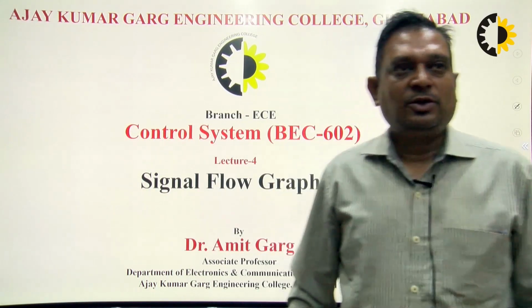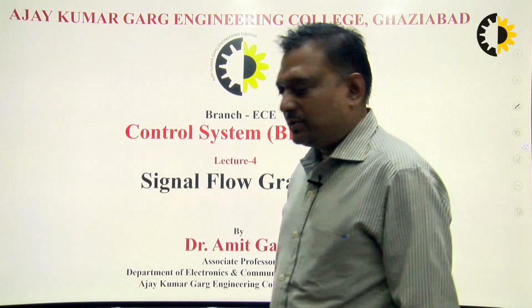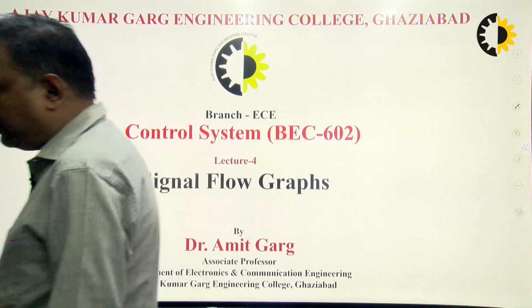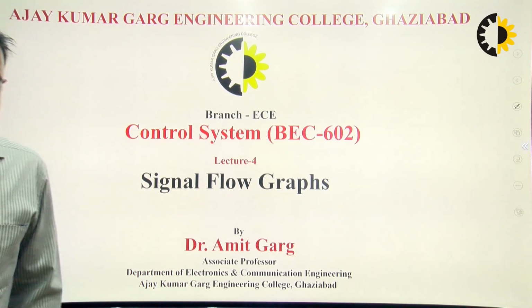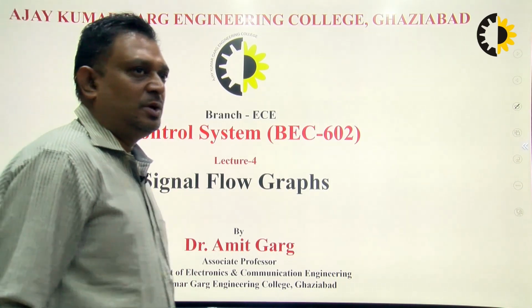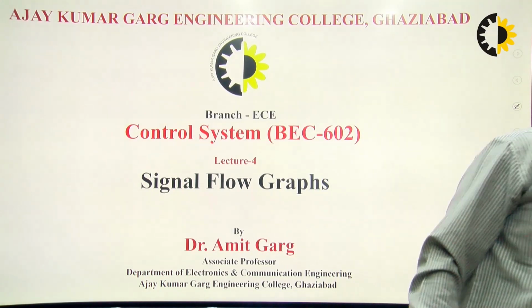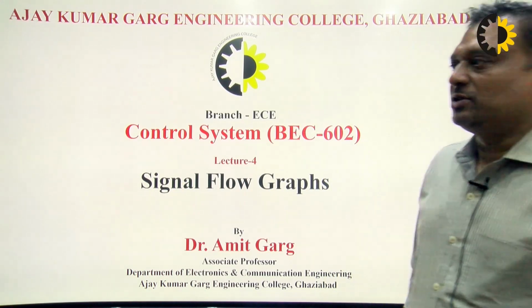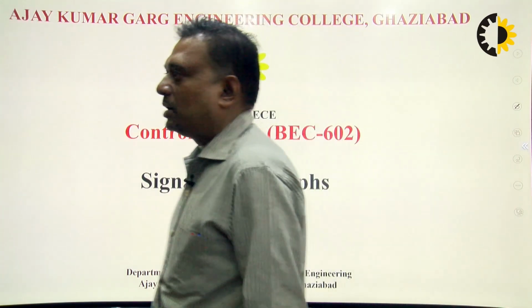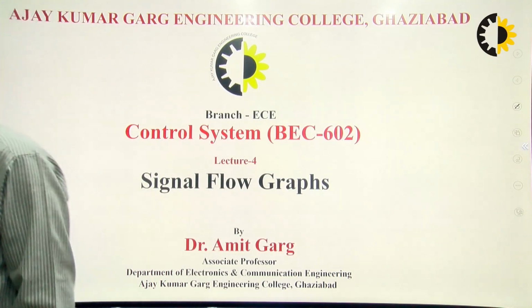Today's topic of lecture is signal flow graphs. Signal flow graphs are a simpler representation of a system by branches and nodes, and by drawing the signal flow graph of a system, we can easily find out the overall transfer function of that given system.